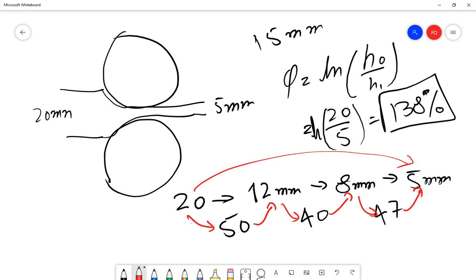And then it is easier, because the rolls would be of adequate size, and the process would be such that the friction coefficient required would not exceed the actual friction coefficient present there, and we will have a grabbing condition and will be able to roll it. So that is how we do multi-step rolling to achieve our required thicknesses, from a very large thickness to a very small, fine thickness. But yes, keep all the conditions fixed.